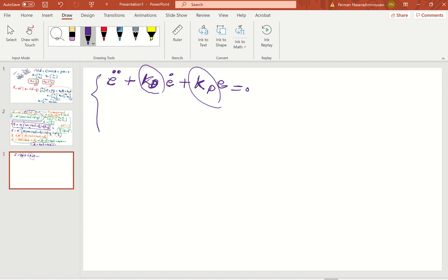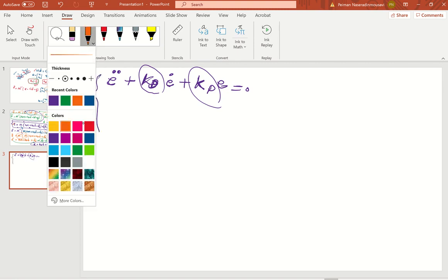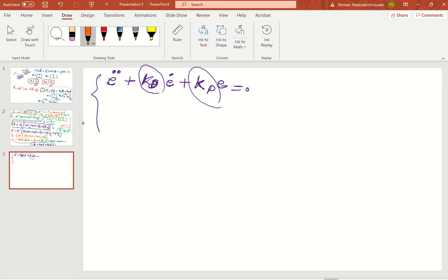Remember, if you compare this with our famous relation I taught in the undergraduate vibration and control course, that was x double dot, remember, mass spring damper, plus 2 zeta omega n x dot plus omega n square x is 0. It was the damping ratio and omega n. Now we can say, I want the robot to be underdamped. Underdamped behavior means it has a peak and oscillation. That's not good. It means you want zeta smaller than 1.